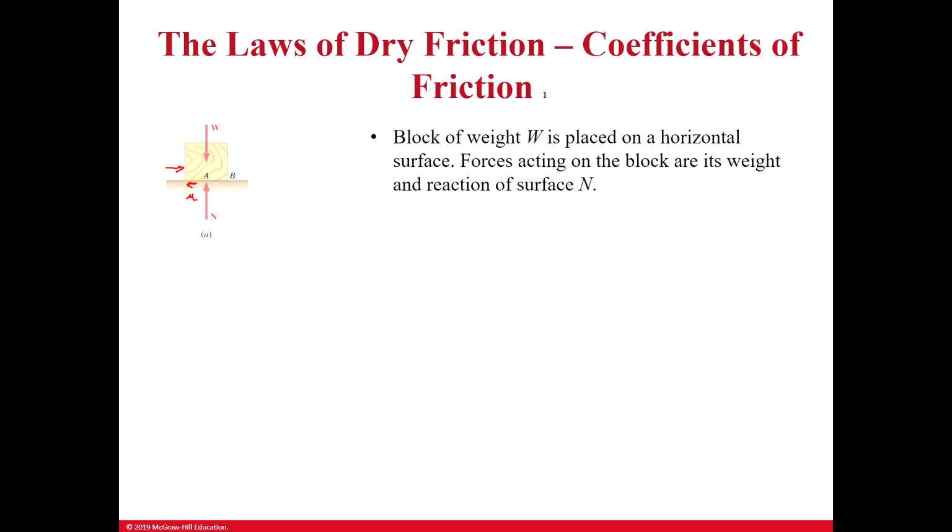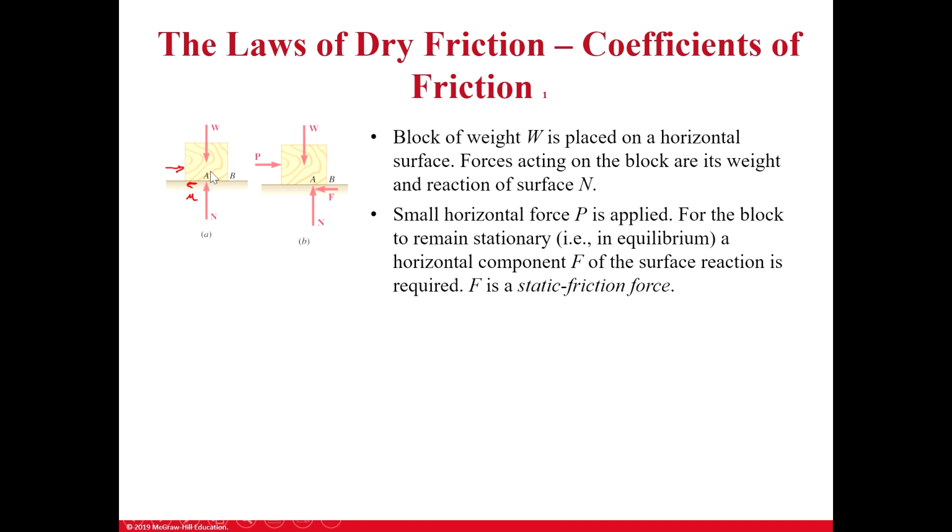That is given by a friction coefficient. And different materials have different friction coefficients. So the concept is very straightforward. Up until the point where P is equal to F, there's no movement. Velocity equals 0. The moment where P is greater than F, the velocity is different than zero and you have movement. Okay? Then you can move things around. And F is given by the friction coefficient times your pushing force. Okay?